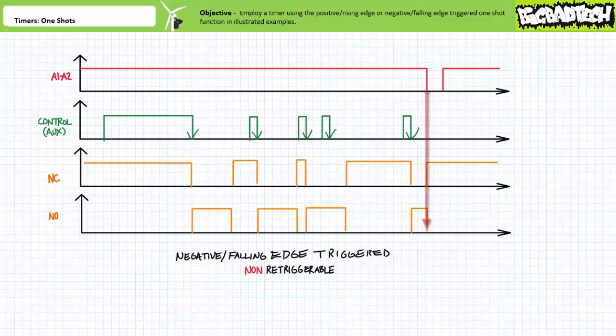As previously, if the timer ever lost power during an ongoing OneShot, the ongoing OneShot would be canceled and reset, and all associated contacts would immediately return to the deactivated state. The restoration of power returns the timer to service.